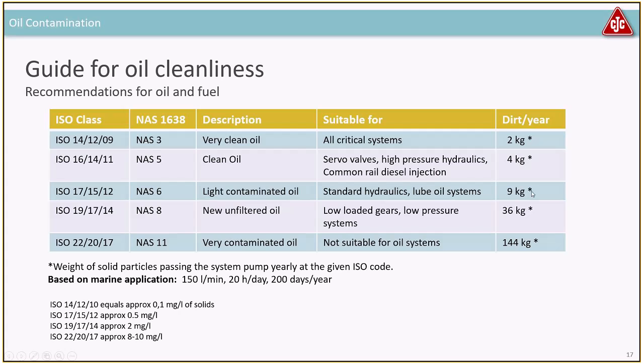So 8 pounds versus 70 pounds, there's a big difference. So of course you'll be wearing out your pump. And the cleaner oil here, it says, is suitable for servo valves, high pressure hydraulics, common rail diesel, and so on. So the more of the dirty oil you circulate over the system, the more will wear.